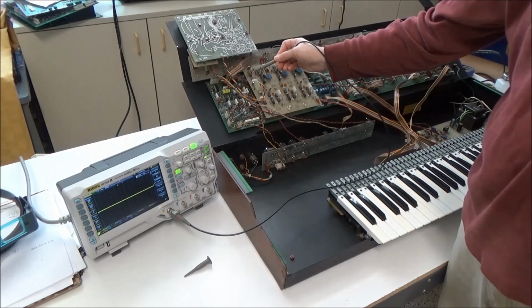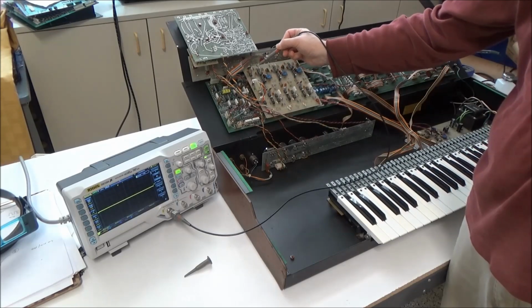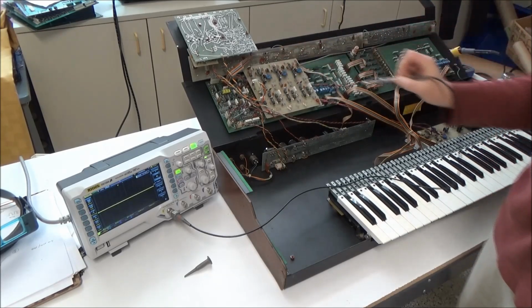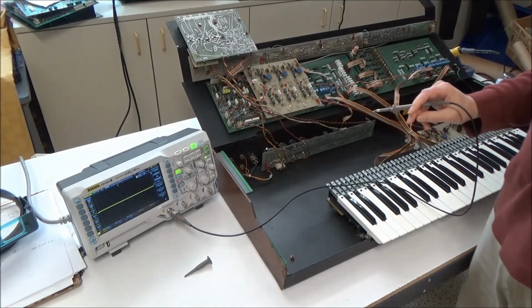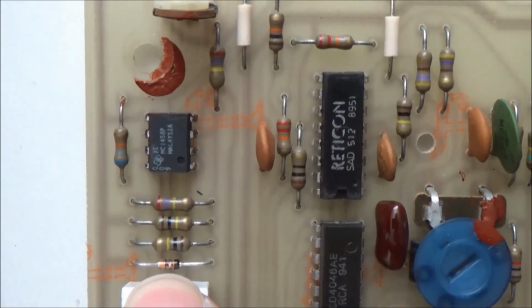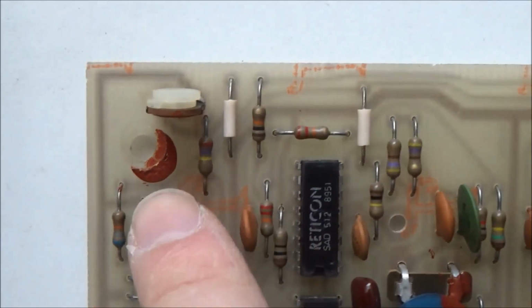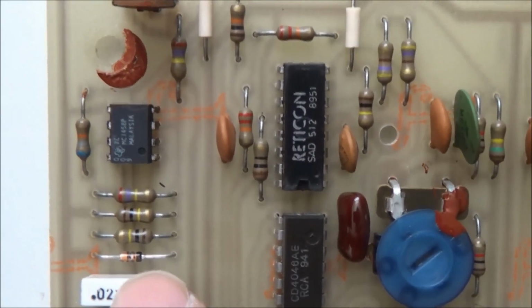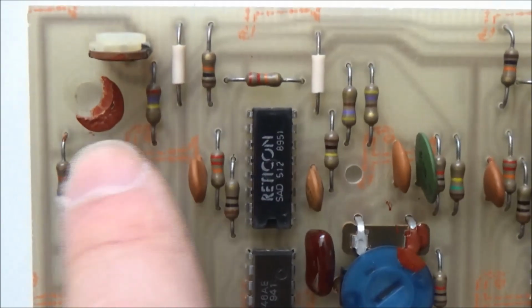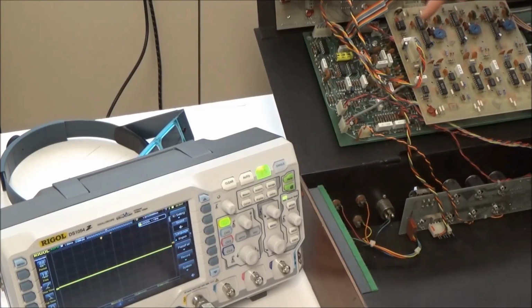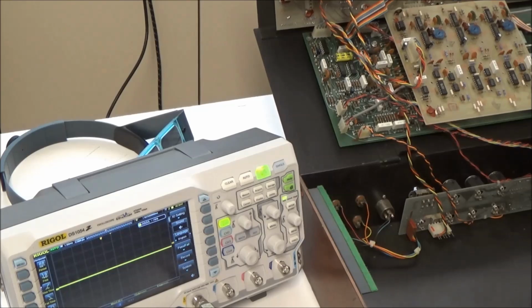If it's not, then we can take a look at some of the passive components, the resistors and capacitors in the circuit around this. But for starters, let's pull this op amp and replace it and see if that fixes our noise. So here's that section of the board, and I saw kind of hiding behind this capacitor, there's a diode there in the circuit that's connected to the output of this op amp, and diodes can also get noisy. They're a semiconductor device, and they can get noisy. So while I'm pulling out the op amp, I'm also going to pull out this diode and replace it as well.